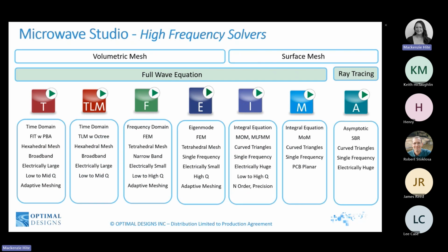Microwave Studio includes 7 high frequency solvers, including 2 general purpose solvers, the time domain and frequency domain, as well as more purpose specific solvers of eigenmode, integral, method of moments, and asymptotic. This slide conveys the mathematical technique and meshing type per solver.